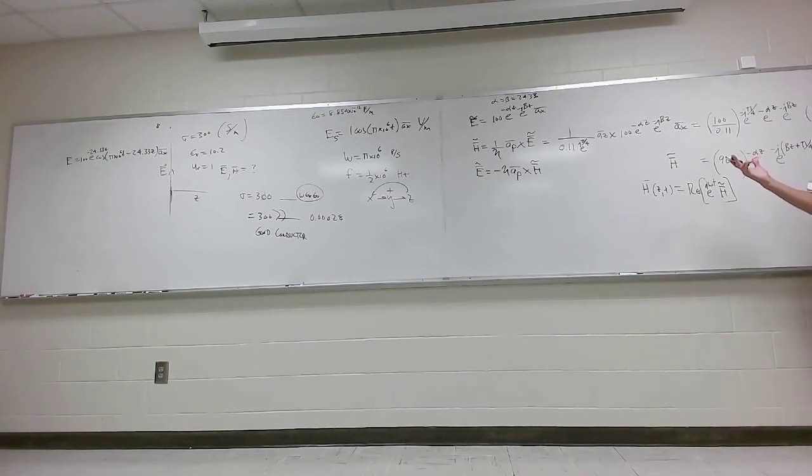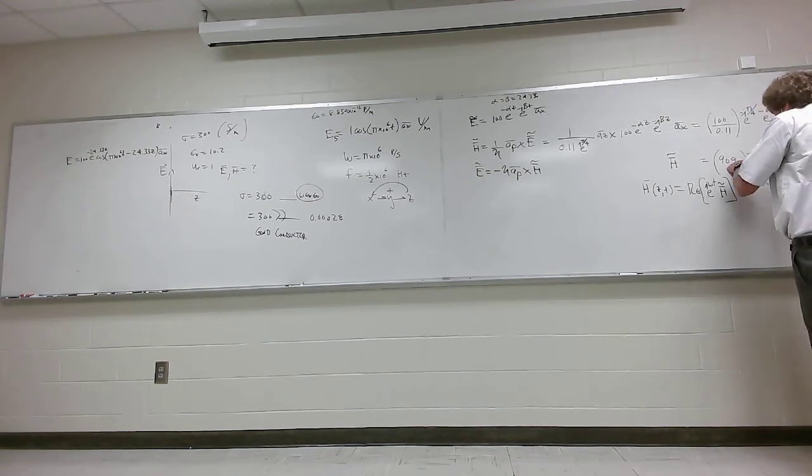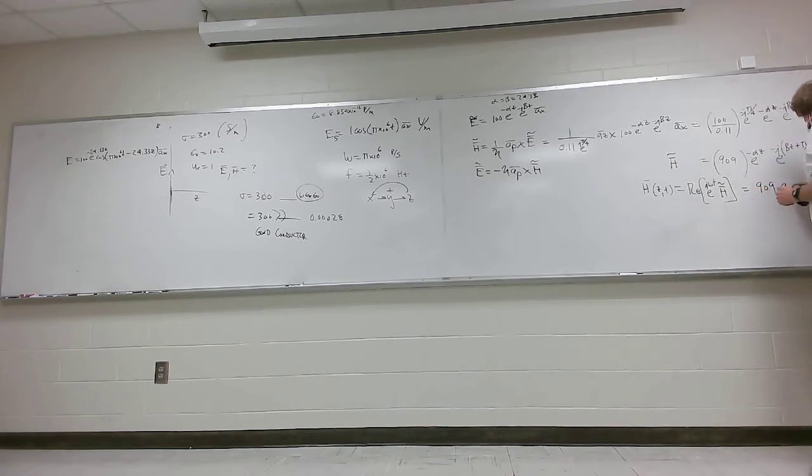But really what I'm going to do is take these two terms, and I'm going to get a cosine form. Am I not, class? Y'all remember that? What's going to come out of this is this. Same magnitude, 909 approximately. e to the minus alpha z, that's fine. Now, this is the part that I have to expand in cosine plus j sine, right?